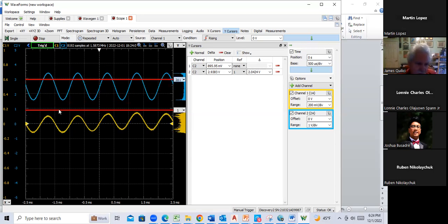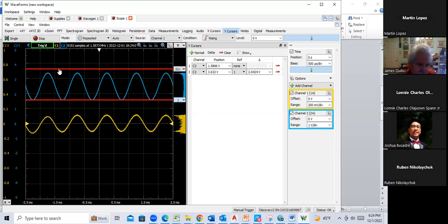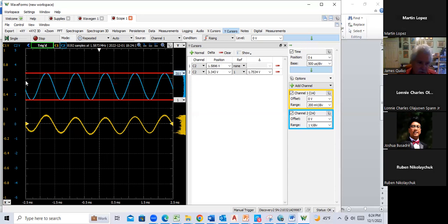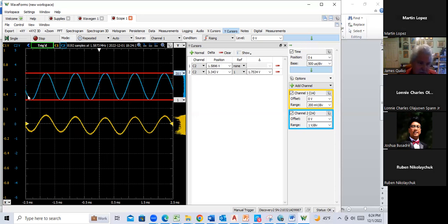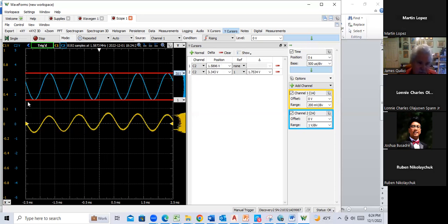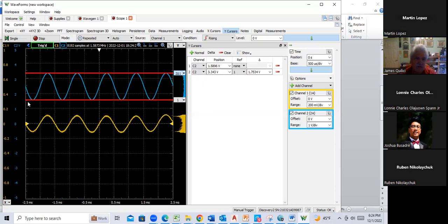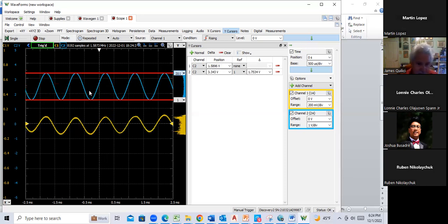So what I did is I reduced my collector voltage, and in doing so, again, it's the collector current, the supply voltage minus the collector current times the collector resistor determines where the collector voltage is. So by reducing, I was sitting down there at 2, I reduced it from 2K to 1.5K. Now it's looking pretty good. It's oscillating around 2.5, which is a good spot to be.